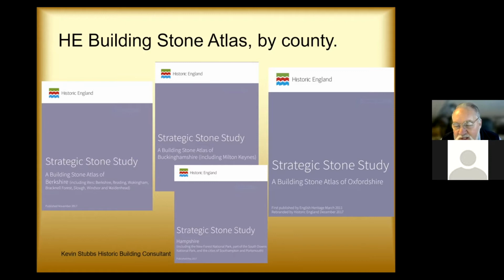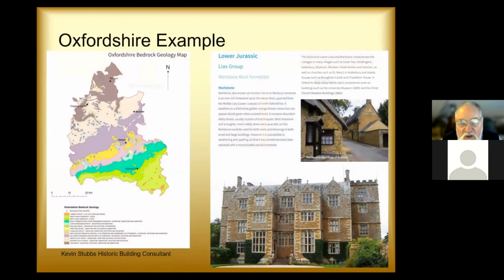And they also indicate which quarries are still available, and there are very, very few of them still producing stone for matching your material. So quite a lot of stone repairs these days are done with material that's brought in from elsewhere, particularly from France, that are a close match rather than a good geological match for your buildings. And as I say, it's a very good source.